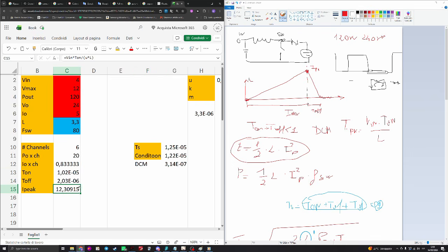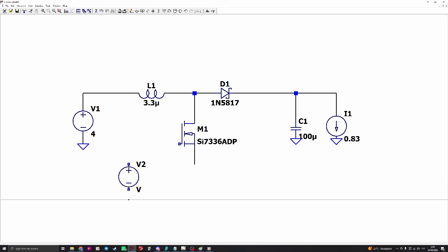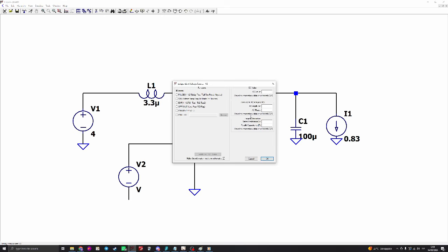Okay, so the peak is 12.13 in this condition. Let's see immediately. Let's use now in this stage we can use this one. Then I will make a proper design for the turn on. So between the pulse, it will be between 0 and 15. Okay, rise 1 nano, and T on will be, of course.